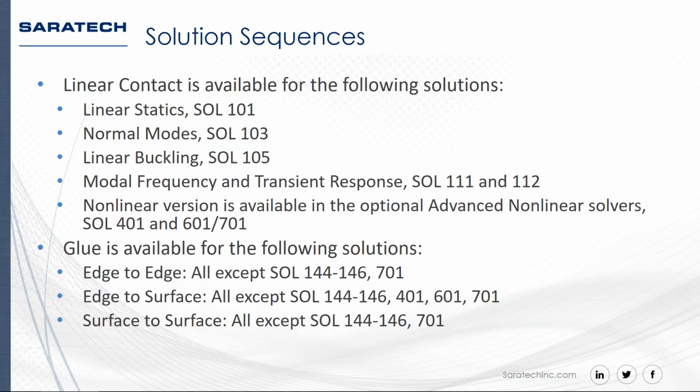All right, so as for these solution sequences, linear contact is available in, like I said, most of the linear ones: linear statics 101, your normal modes for your natural frequencies 103, buckling 105. Also the modal frequency and transient responses, 111 and 112. And also the multi-step nonlinear 401 and the advanced nonlinear 601 and 701. So notice, again, the basic nonlinear 106 is not included there.